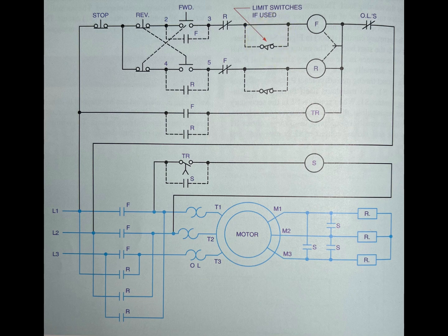Automatic acceleration using frequency relays. Definite timers or compensated timers may be used to control the acceleration of wound rotor motors. Definite timers, which usually consist of pneumatic or dashpot relays, are set for the highest load current and remain at the same setting regardless of the load.